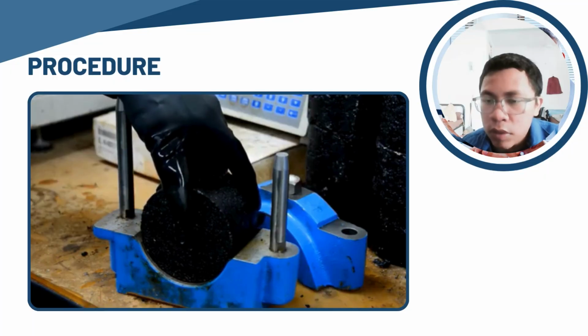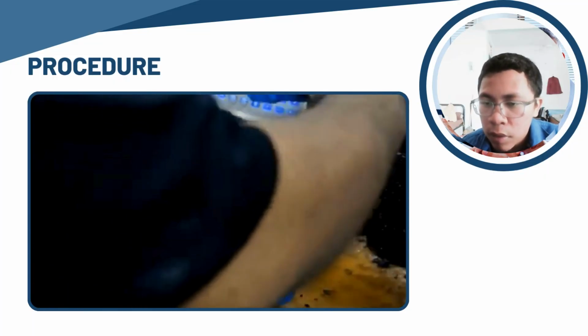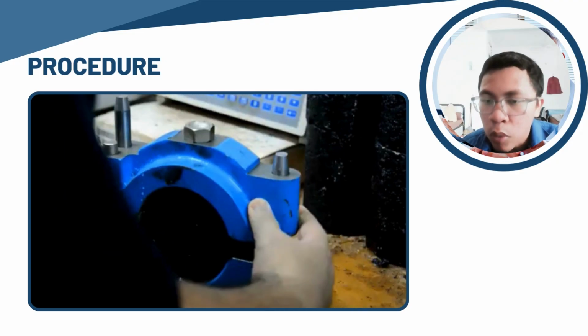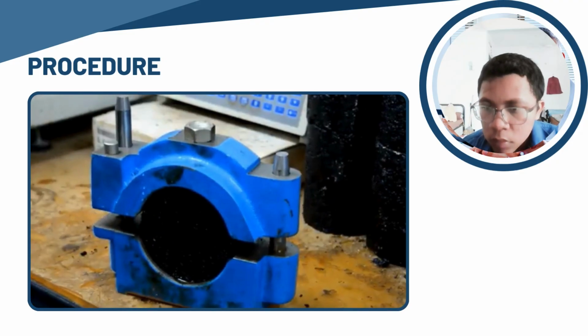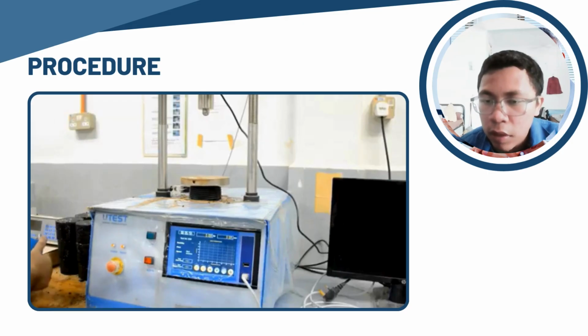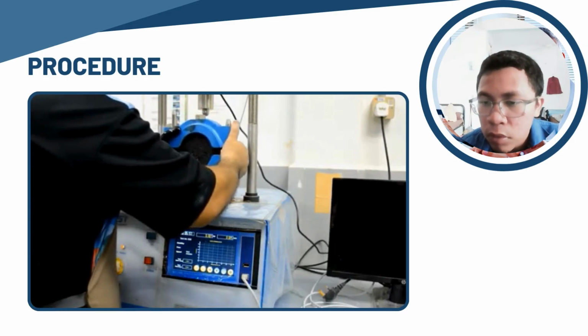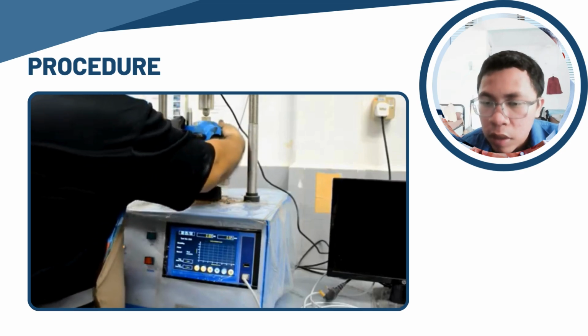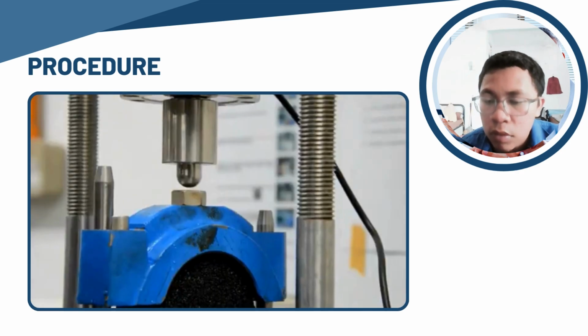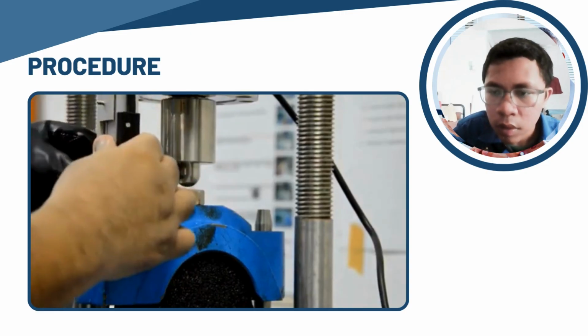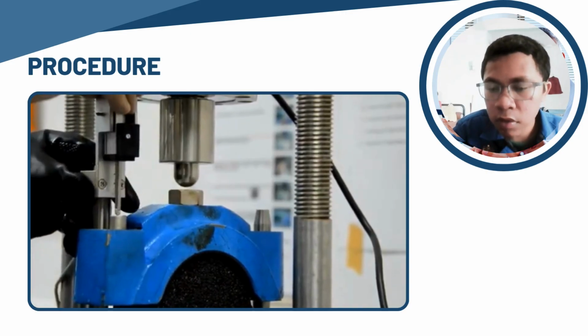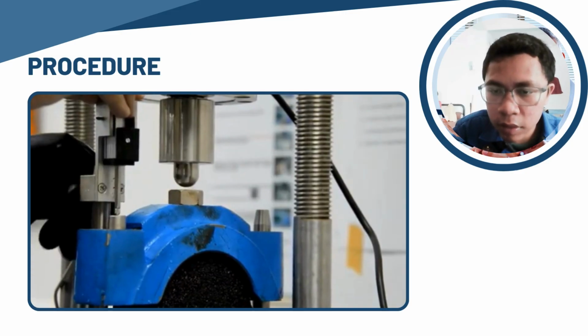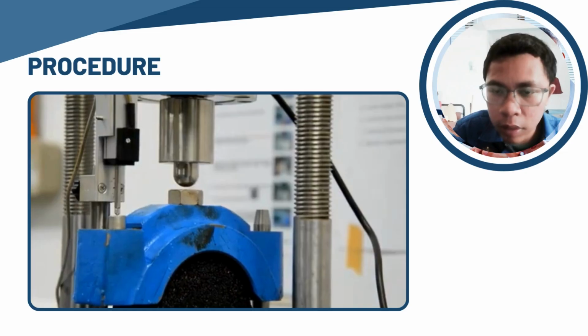Use an extruder to remove each specimen by taking the specimen up through the hole, keeping the specimen as perpendicular as possible so that the specimen isn't distorted. Measure the specimen height and weight in air and water.